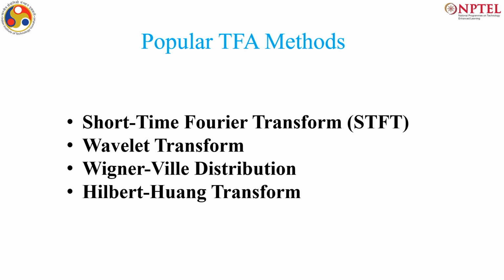Let us understand what are the popular time frequency analysis methods. So, the first is short term Fourier transform. So, what is short term Fourier transform? As the name suggests, it is a Fourier transform which gives me frequency, but it is a short time, like I will not do the Fourier transform of the whole signal together. I will take small windows, do the Fourier analysis, another window Fourier analysis, and in this manner I can get the spectra of each window. But typically this window size is kept same in short time Fourier transform.